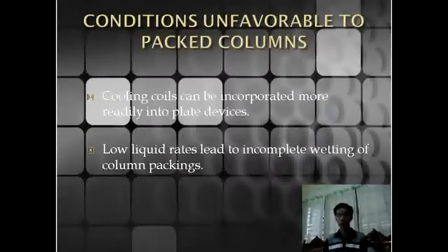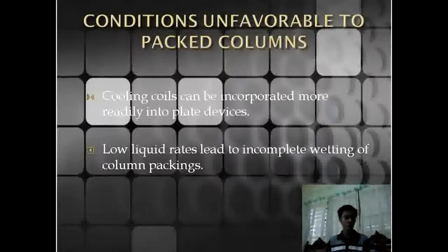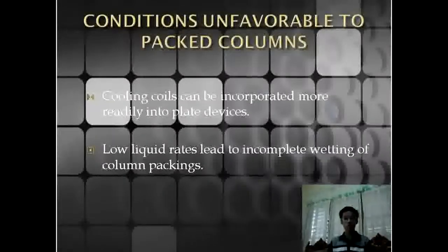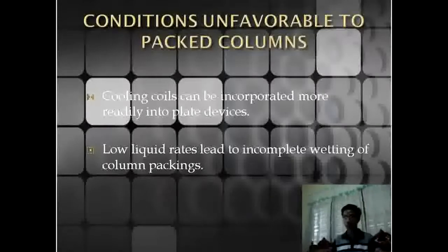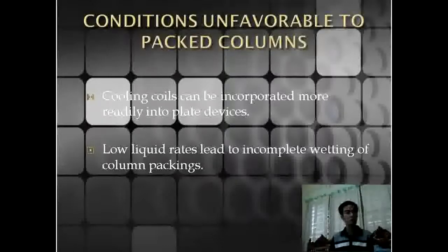To reduce thermal effects, tray columns offer devices such as cooling coils. The low liquid rates in packed columns may also result in incomplete wetting of the packings, and thus decrease contacting efficiency.